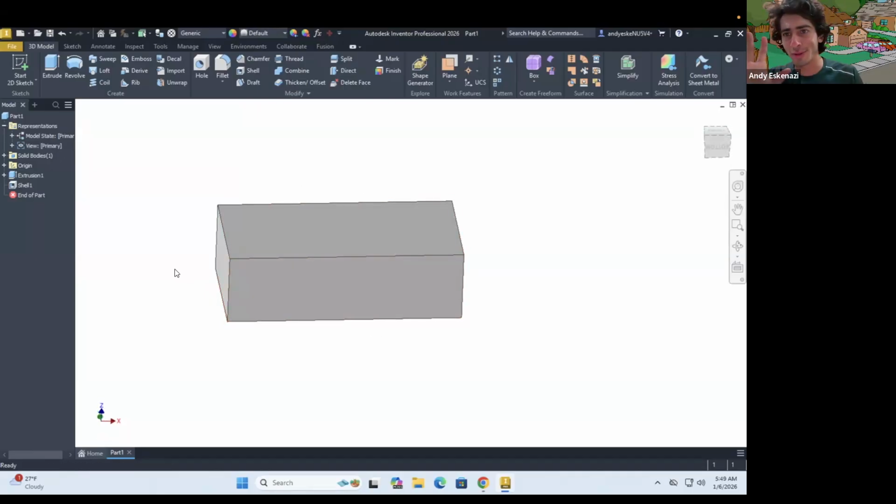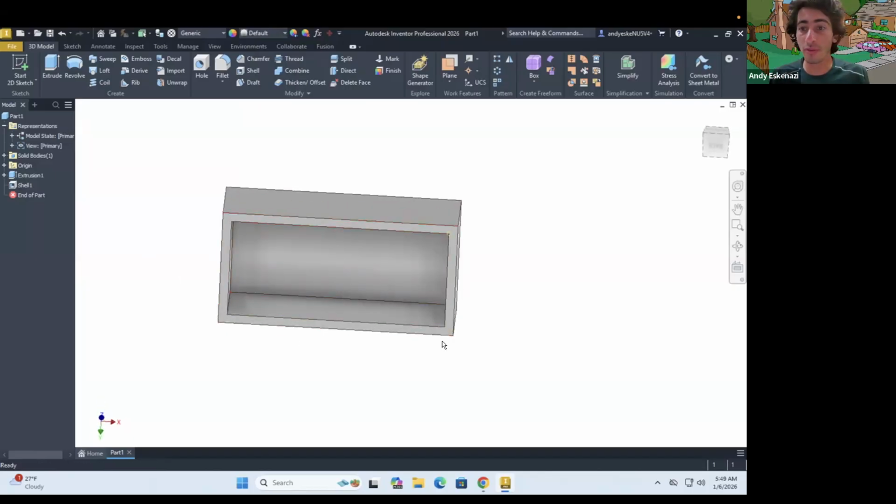And just a rule of thumb, as a side note, whenever you're doing design for manufacturing, especially for things that are going to be injection molded like a Lego brick, you always want to have uniform wall thickness. If you do non-uniform wall thickness, I think you're messing up some of the quality of the parts.